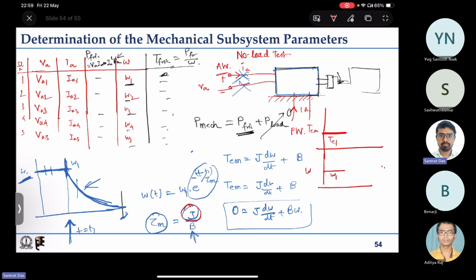Now because you can change torque quite fast, you increase torque from Te1 to Te2 in an instant by giving a step change, or by increasing the current quite fast. Now current will take some time to rise, but in a time window relating to the mechanical time constant, which is in seconds, that rise time will be negligible in the torque waveform, so it will appear as almost a step change.